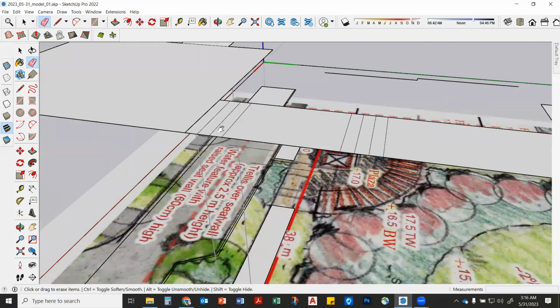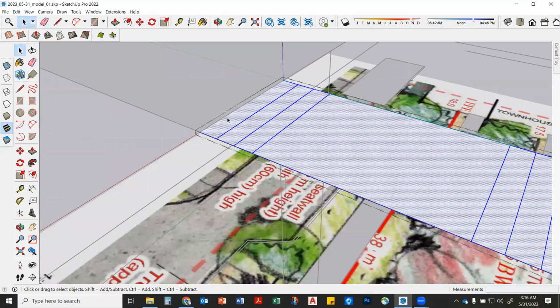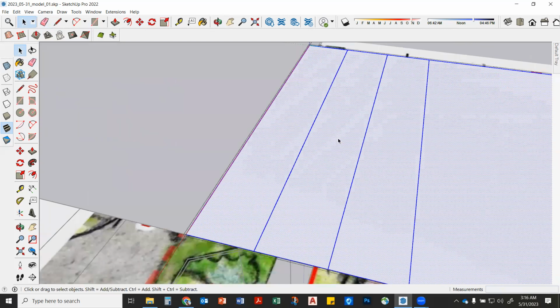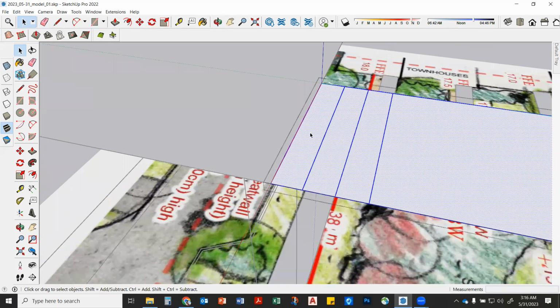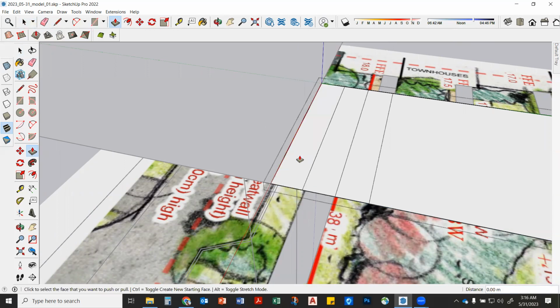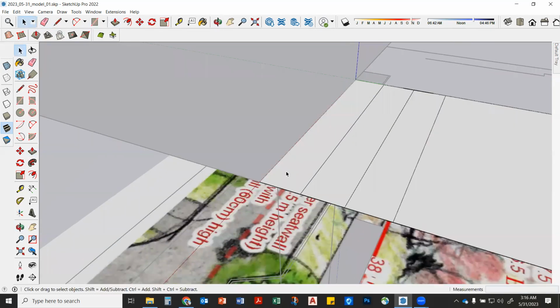But watch, all right, so I'm gonna come in here, we're gonna do our risers. Now watch, what I like to do is make all my risers the same height. So I'm gonna make them a component. So I'm gonna watch inside this group, okay? You don't have to do this. You could just come in and go push and start pushing and pulling this, right? So P is your push-pull shortcut, okay? P gets you in this command. We can do this, right? Everybody tracking? Yeah. You guys have done some pushing and pulling, yeah? Yeah. In SketchUp. Okay. Right?